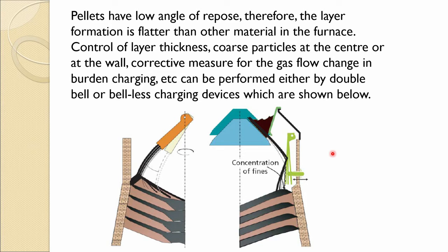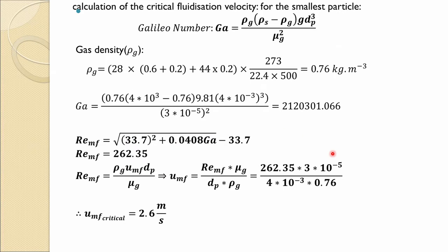Okay, so I think you got the idea from this size distribution, how it can affect and how you can select the velocity. This operating velocity is not related to the larger size particles, it is much more related to the smaller size particles. So, you should be operating your reactor with respect to the smaller size of particles, so that they do not get fluidized.